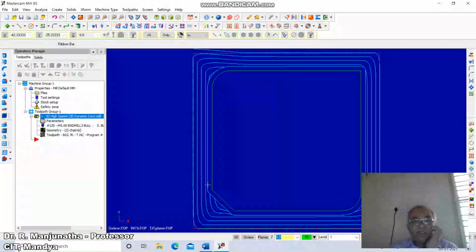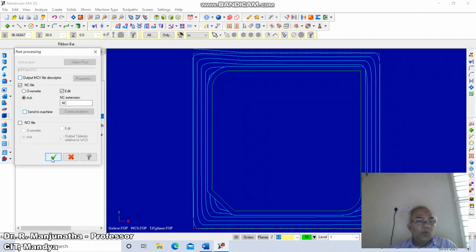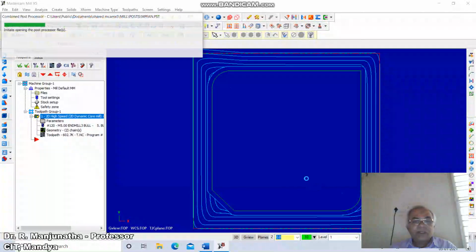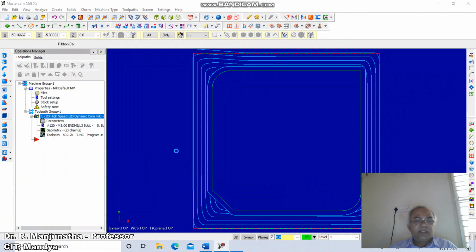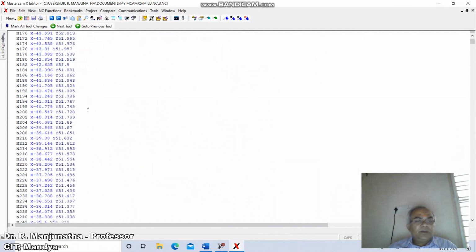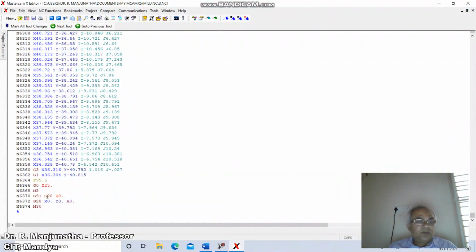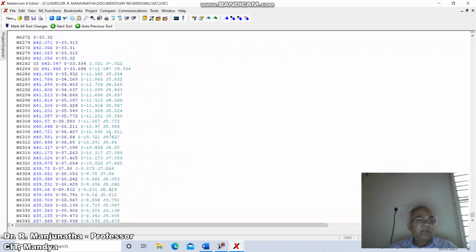Now the machining will take place and you are going to get the profile done. Then click on generate NC codes. Click on G1, click on OK. Now I need to give the value 3. I will save this. So this will be the automatic generation of NC codes for the profile to be machined. About 8095 lines have been generated.